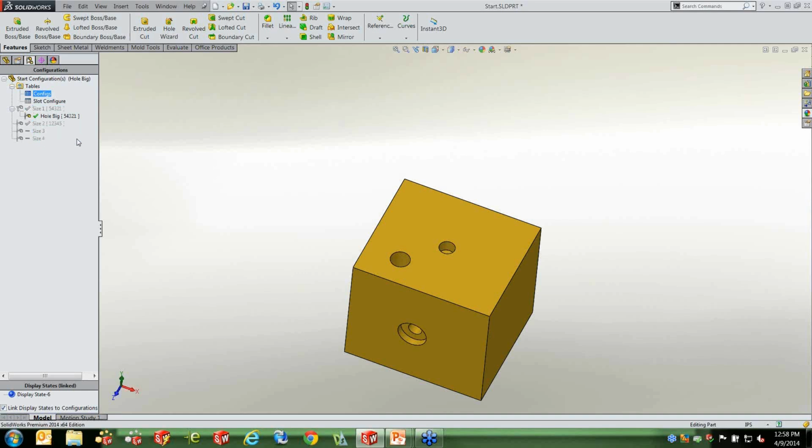It's got to reload that information. Unless you add what we call a rebuild or a save mark. A rebuild and save mark is done through a right-click option inside the configuration manager. And what that says is that each time you save, it's going to rebuild and store that information, so next time it opens up, this is active and ready for you.